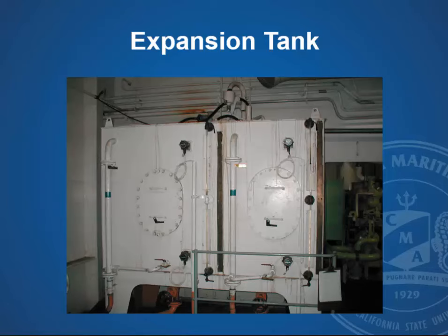If you were to add too much water while the vessel's in port and that expansion tank is fairly cold, then as you start up the main engine and that water heats up, you'll overflow the tank. So it allows for expansion. It serves as a reservoir of fluid.